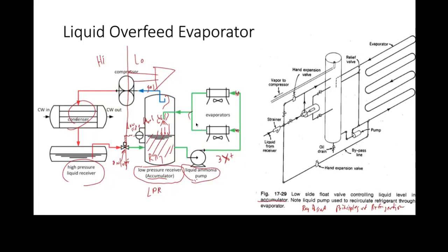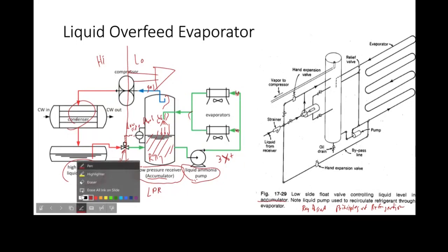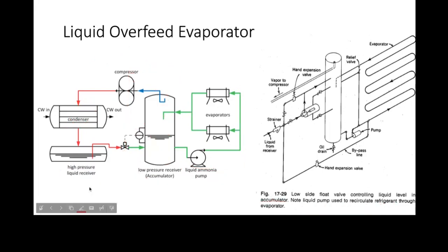When you look at this thing, I want you to think of it as being like a boiler. So what have we got here? A steam drum. And here we've got our heat source. So we've got a room that's hot, right? So this is like our furnace. And so what we have here are risers, and we've got internal recirculation. And we've got a steam separator device in there, cyclone separator, chevron, right?